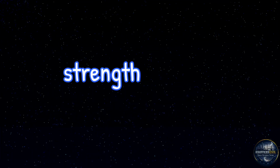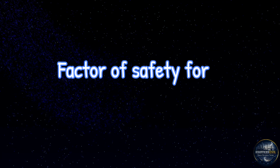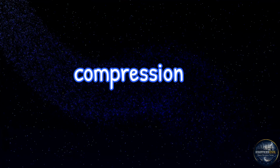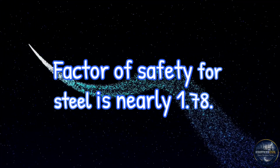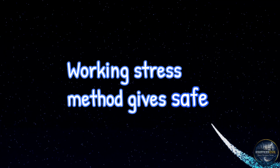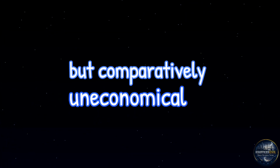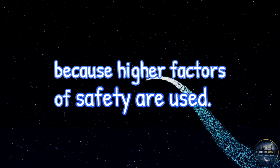Factor of safety is applied on material strength to obtain permissible stress. Factor of safety for concrete in bending compression is nearly 3. Factor of safety for steel is nearly 1.78. Working stress method gives safe design, but comparatively uneconomical sections because higher factors of safety are used.